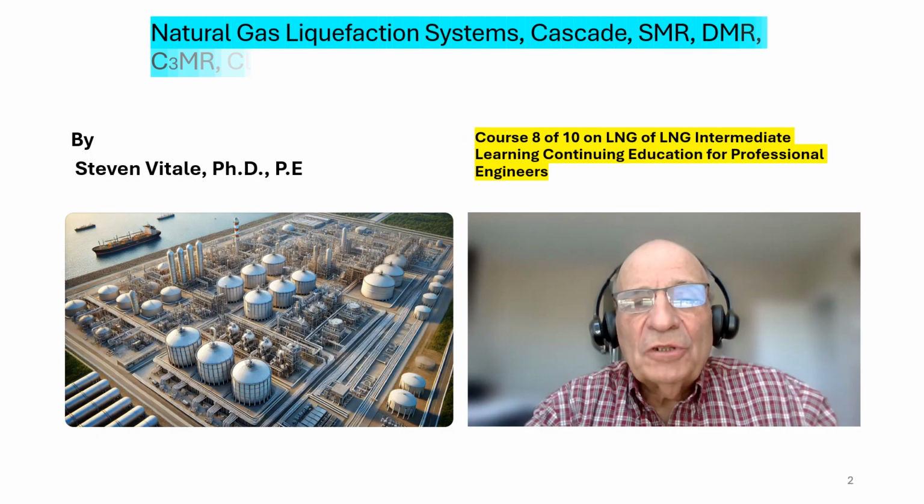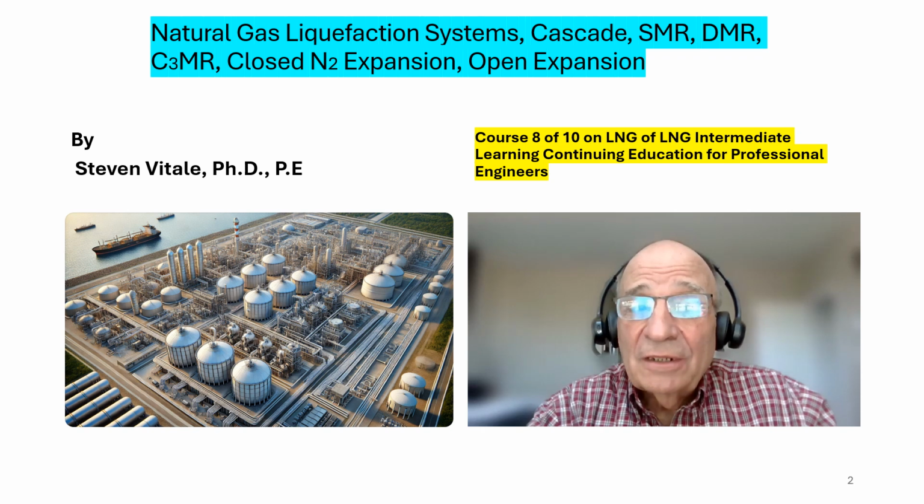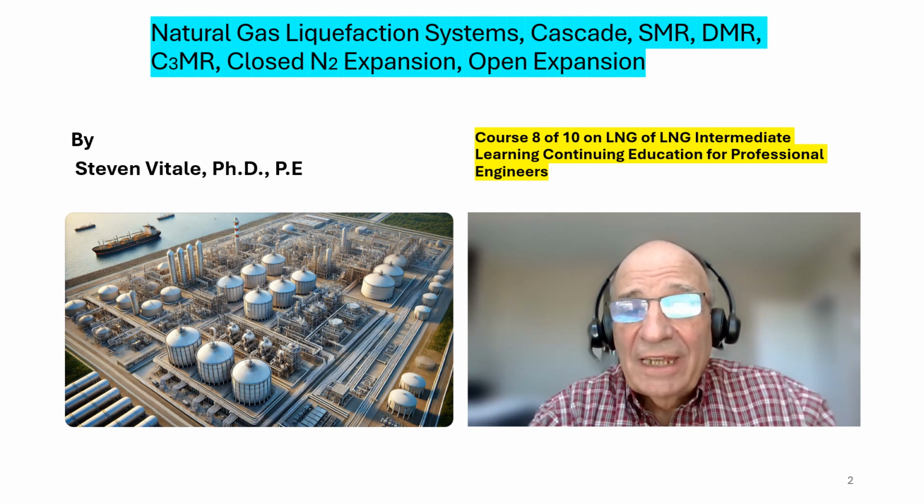In this course, we will talk about natural gas liquefaction systems: cascade, single mixed refrigerant, dual mixed refrigerant, C3MR, closed nitrogen expansion systems, and open expansion systems. This is course 8 of 10 on LNG intermediate learning, continuing education for professional engineers.